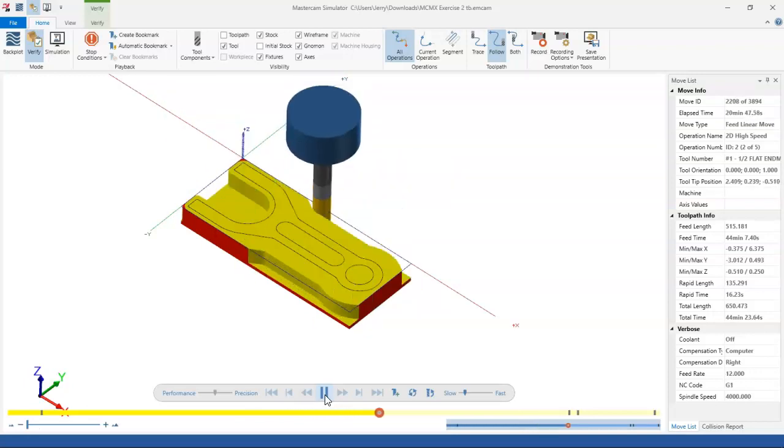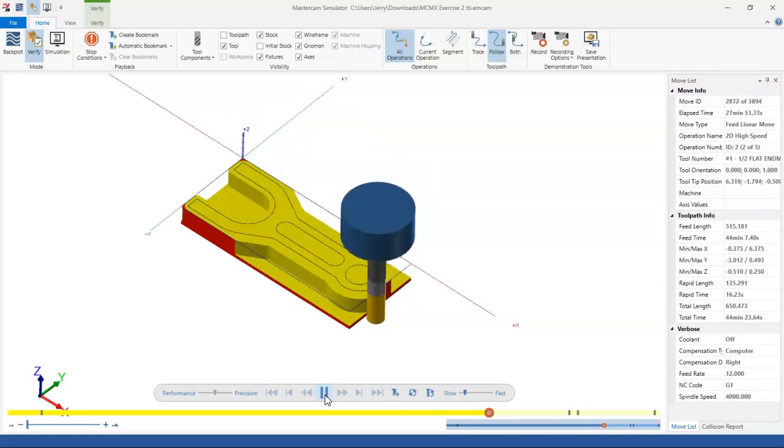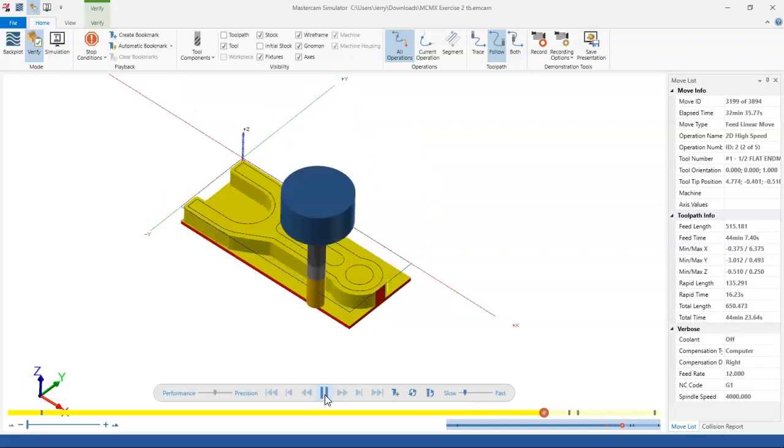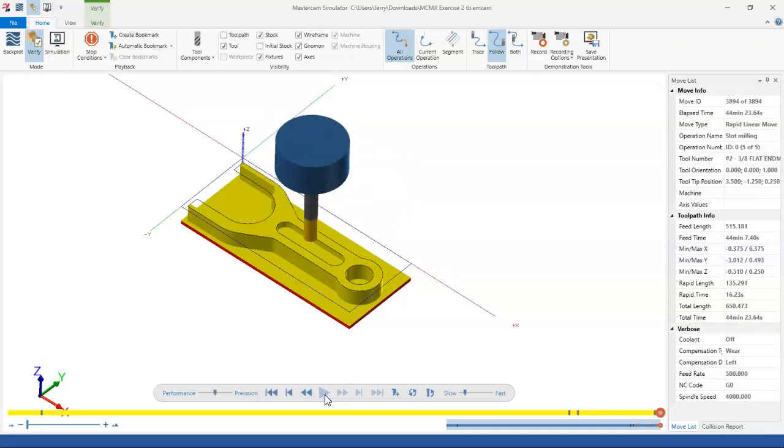Each of the programs that have a high-speed module does theirs a little bit different. SolidCAM does theirs a little bit different. HSM does theirs a little bit different. Each one has its own little idiosyncrasies, but the idea is to reduce that tool load and get longer tool life while you're making those cuts. I had the same reaction. On the first Turbo cuts, I saw that and thought, that's a monumental waste of time. Why would I ever do that? And then you start making the cuts and you go, oh, that's why I would do that. Yes.